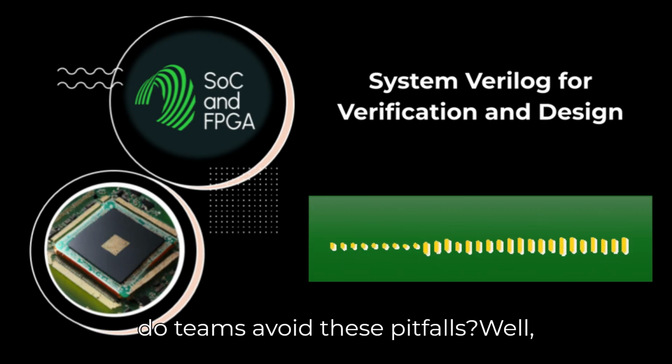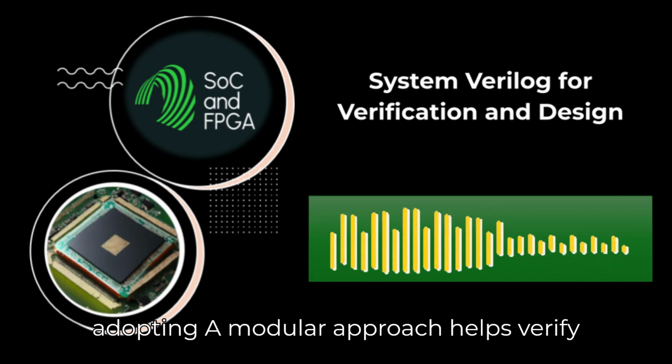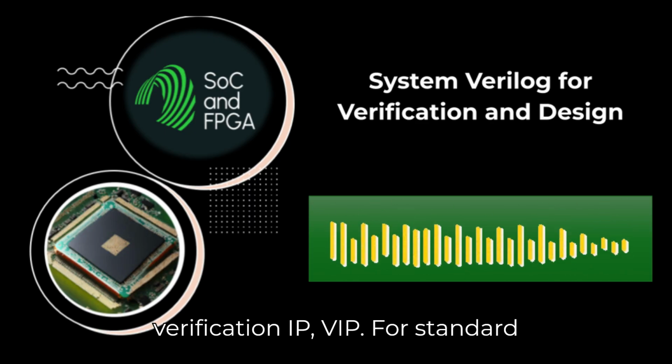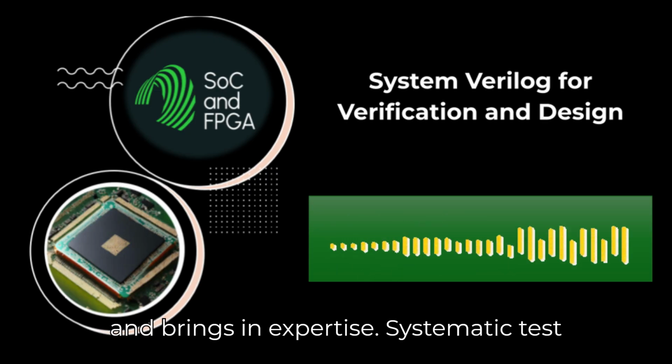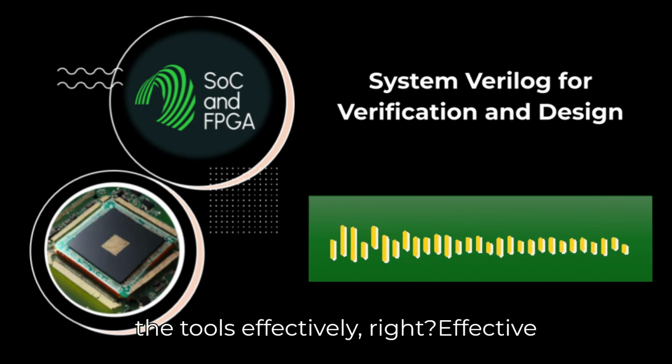So how do teams avoid these pitfalls? Well, adopting a modular approach helps verify smaller blocks thoroughly before integrating them. Leveraging commercial verification IP, VIP, for standard interfaces saves a huge amount of effort and brings in expertise. Systematic test planning is crucial. Clearly define what needs to be verified up front. And using the tools effectively.